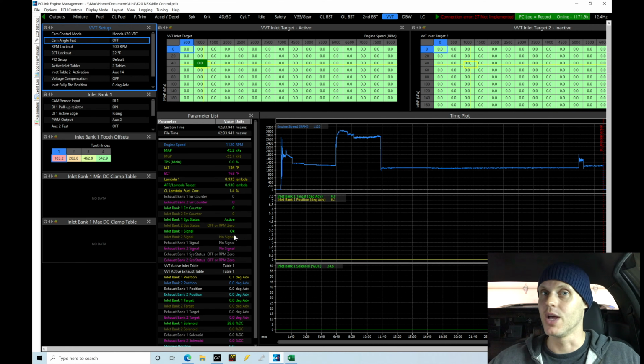Now I can tell you, if you've worked with the G4 Plus system for any variable cam control, it worked, but it wasn't the best. The G4X is substantially better for variable cam control. It's much quicker, there's so much less setup. The G4 Plus, we had to go through and manually set all this up and do a test mode. We don't have to do that anymore. This is a really, really awesome feature, and it's an improvement over the G4 Plus with the G4X.